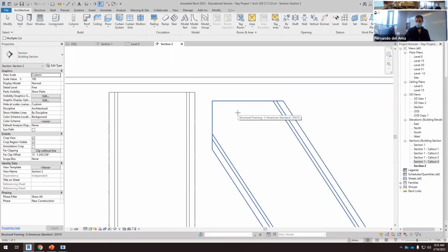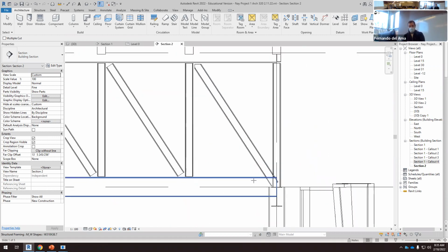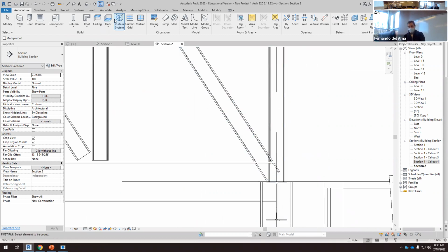There is always a gap between this, because when we are working with these steel elements, we have to weld this, and welding means that we are adding material here. So there is always a gap. This gap can be something very tiny like that, because we have to add material, heat it up and weld it all around. So that's why we have this gap between this and that. But anyway, this is the shape that we will end up having here.